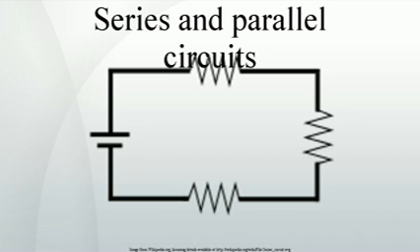However, if the inductances are not equal and the coils are tightly coupled, there can be near short-circuit conditions and high circulating currents for both positive and negative values of M, which can cause problems. More than three inductors becomes more complex, and the mutual inductance of each inductor on each other inductor and their influence on each other must be considered.